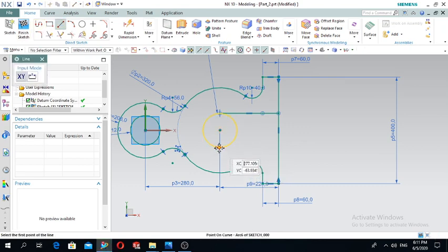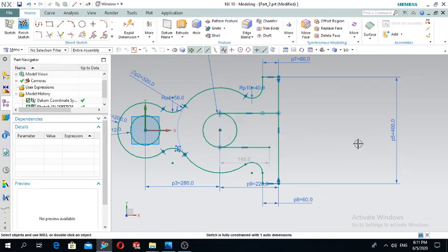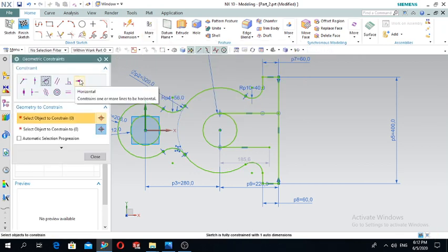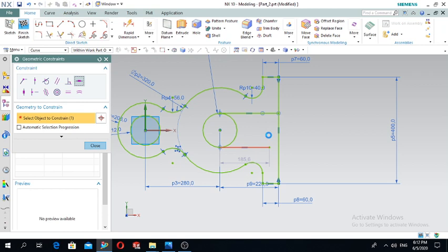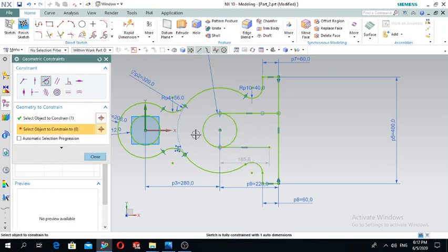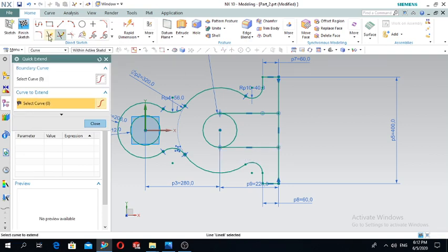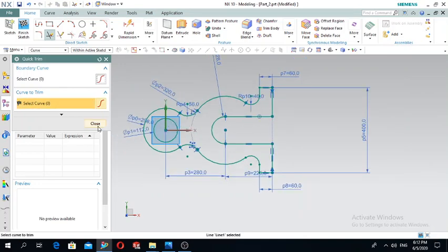let's draw here the line. It is angled, a little bit inclined, so in order to check that geometric constraint, that horizontal, this one. Okay, it already exists, so tangency, this one with this one, it already exists. So just to check if it's correct or not, quick extend this one and trim this one and this one.